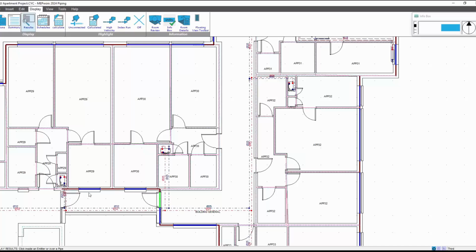So as you move up towards the entry point, once you get to the 7th appliance, in line with codes of practice, the diversity remains the same. It uses the same factor each time. Obviously that will adjust the flow rates, but the factor used will be the same after the 7th appliance. For more details on the calculations, go and download the codes of practice, and that shows all the calculation methodologies in there, in line with the latest codes of practice issued by CIBSE.